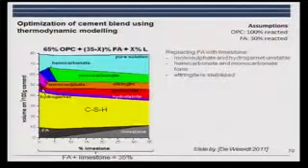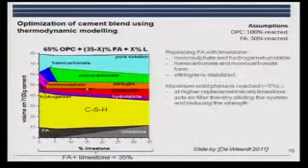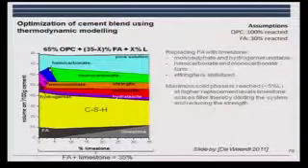You can see that the phases change when we add increasing amounts of limestone, and you can also see that we have an increase in volume of solids, which gives higher strength. And depending on the alumina content of the fly ash, you can optimize the limestone content.